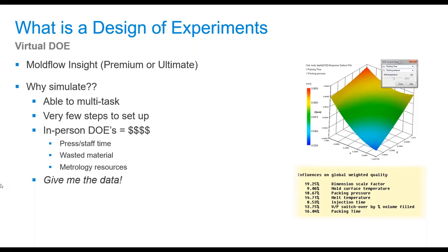Another advantage, hinted in my previous comments, is that the purpose for setting up a virtual DOE is simple. If you've already set up and run the Moldflow analysis, or if you use Moldflow during the part and mold design changes, adding a DOE to the existing simulation involves setting up the type of DOE, variables, and quality criteria. And since it duplicates your original study on those inputs, the existing simulation is untouched, just some new added results.